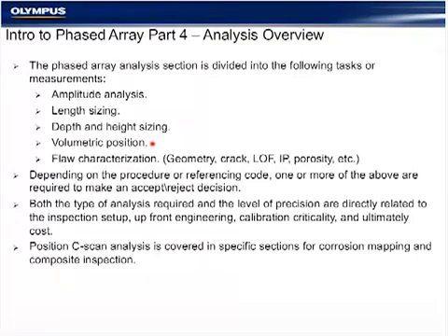The location or volumetric position is normally our number one indicator, next to A-scan characterization and two-sided detection, for telling us what type of flaw it is, meaning porosity, slag. In a typical V-weld, all of the different types of failure mechanisms, lack of penetration, inadequate penetration, and so forth. Again, volumetric position is our key indicator.